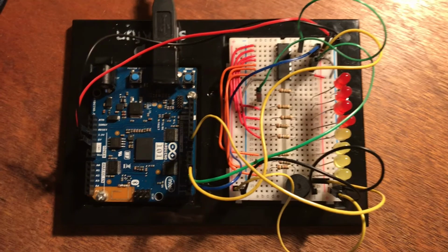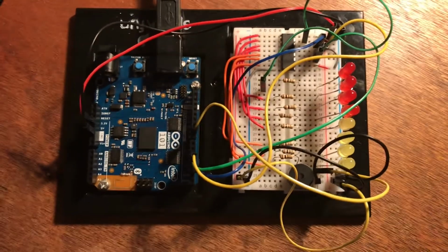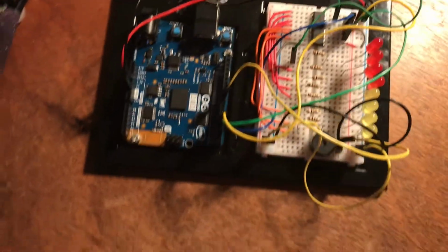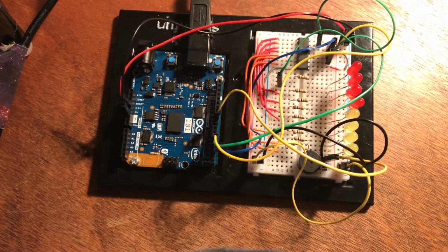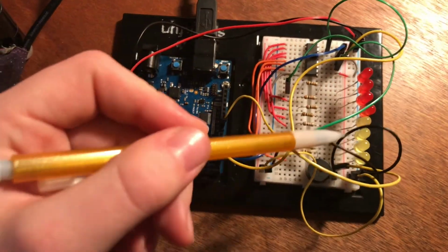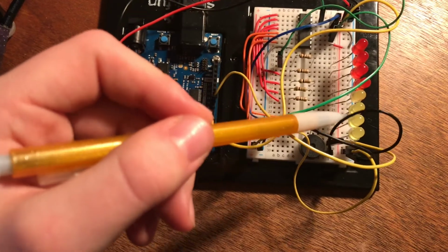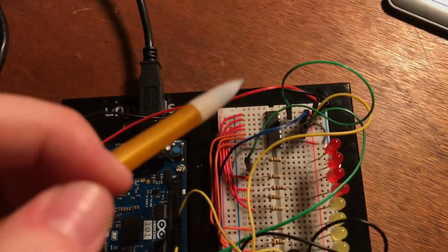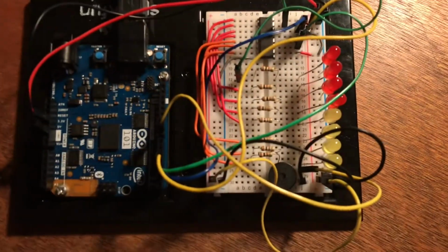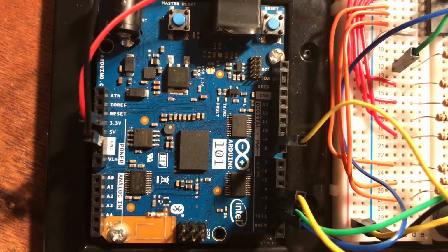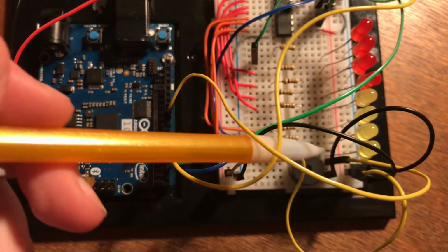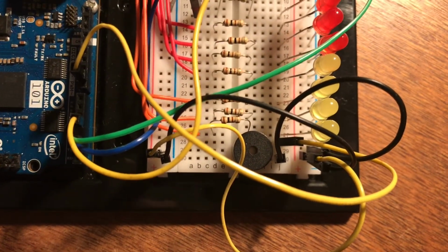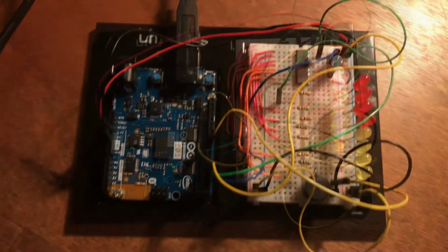Here's the modified board for using a shift register. Everything's the same except for the piezo buzzer is now attached here. It is grounded by this black wire here that is connecting to the negative column on the board. That's grounded by the black wire again over here. And then it's connected to pin number 9 on the board through this yellow wire here, which connects to its positive side. Yep, and then that's it.